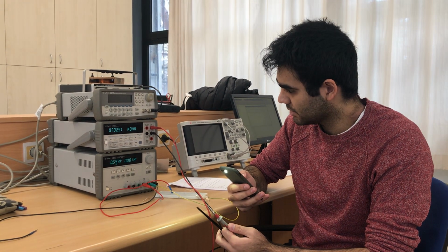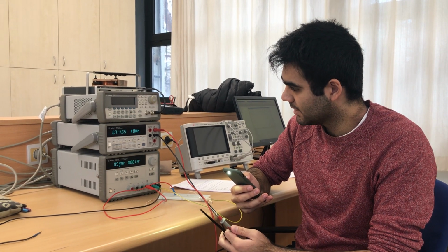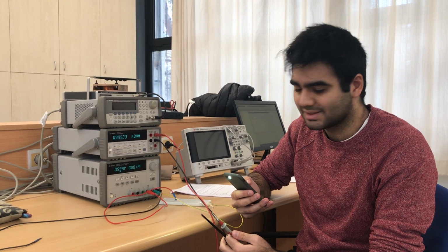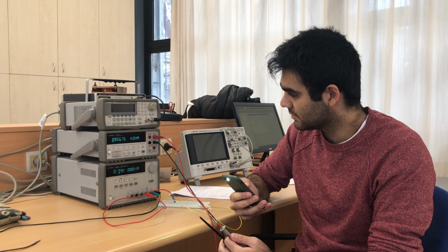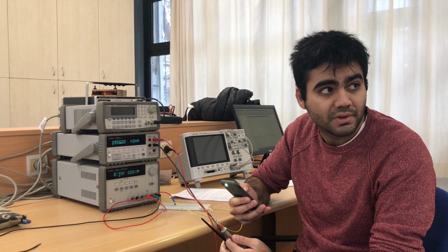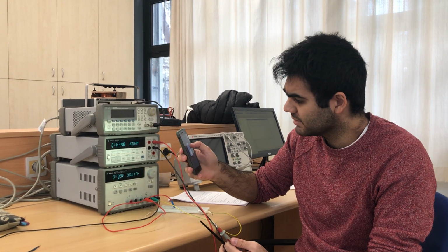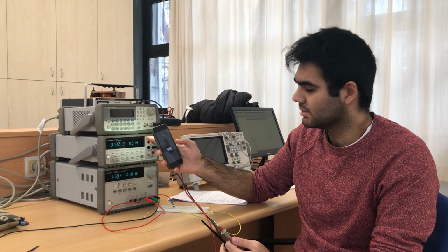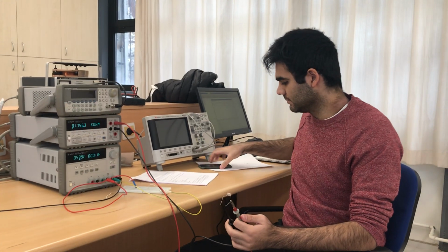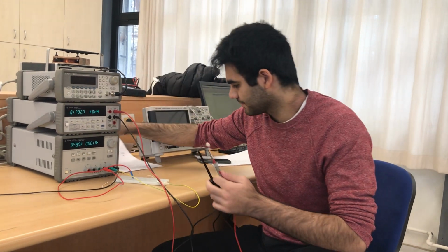Now one more. Now I started to read 0.7 kilo ohms, and I will use the least value. In this least value, I started to read 1 kilo ohm. So we see that when I decrease the light intensity, the resistance value increases. So let me move on to the second part of my experiment.